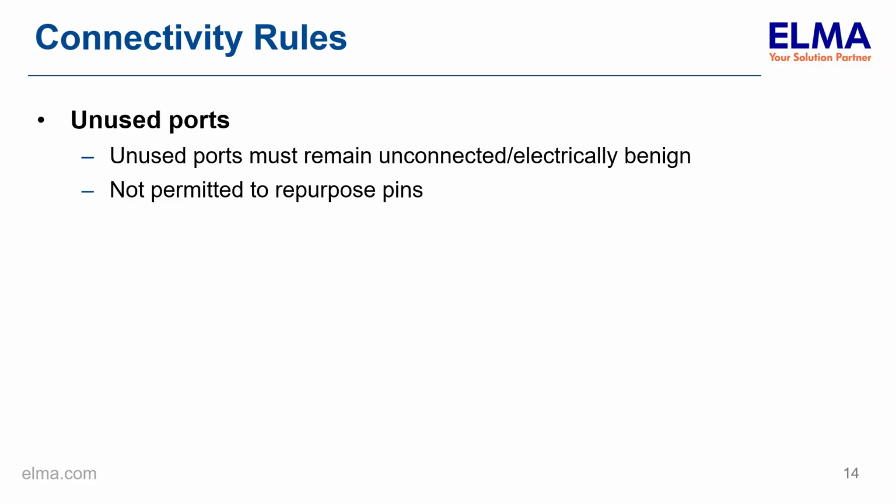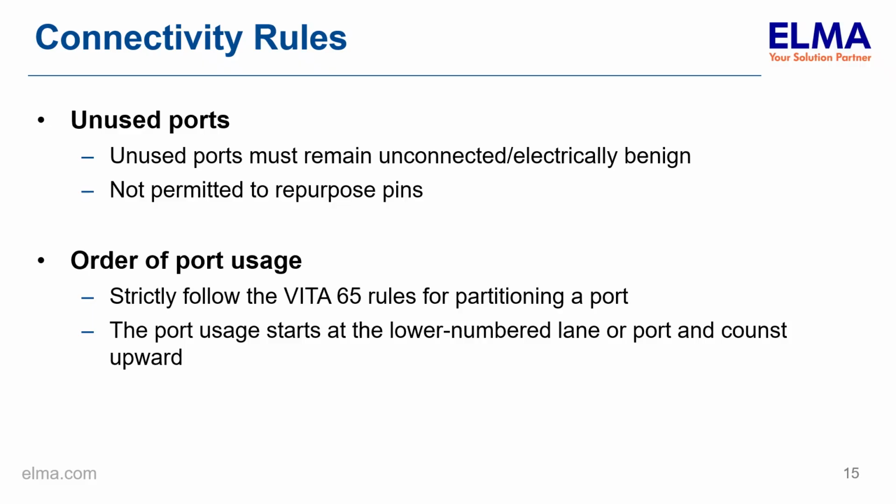In addition, designers are not permitted to repurpose pins for functions other than what the standard defines. If the board designer wants to implement only a portion of a defined port, like only implementing 4 lanes of a PCI Express on an 8-lane expansion plane, they must strictly follow the VITA65 rules for partitioning ports. One important rule is that port usage starts at the lower numbered lane or port and counts upward.